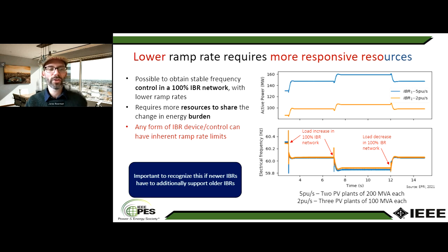So what that means and shows is that the more resources you can build up with capabilities early on, the more resources can later, at a high penetration inverter-based system, provide and deploy that response, which then reduces the burden for each one of the resources. And that is one of the key ideas of 2800, introducing a mandatory requirement for fast frequency response early on, so that once we reach those penetration levels at some hours in the year, in maybe 5, 10, or 15 years, we have enough capability built in the assets to then still operate the system.